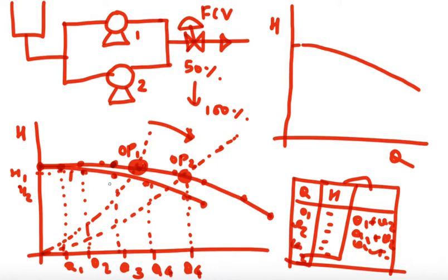At that moment, while operating in parallel, the corresponding flow is here and the corresponding flow is here, and the head is almost the same. So the parallel operation will not give you much advantage of increased flow rate. But if you see toward the end of curve operation, on the right of the pump curve, the gap between the single operation curve and the two-pump parallel operation curve is higher.